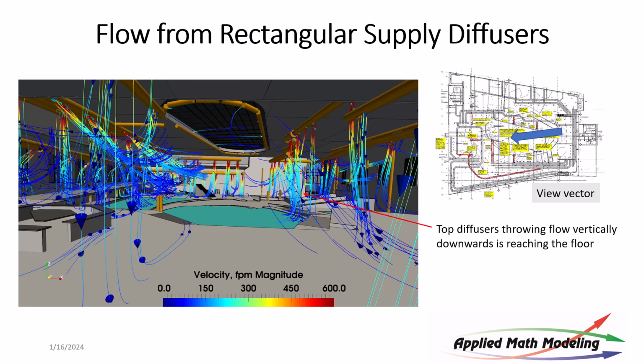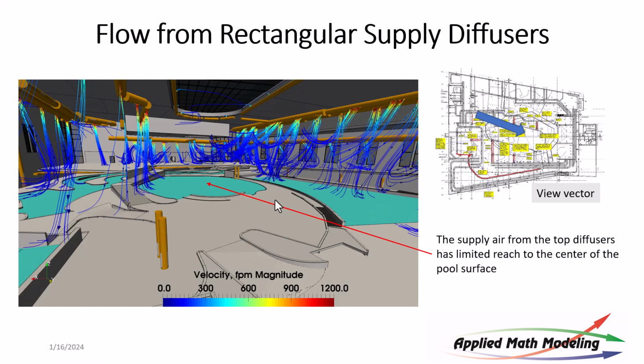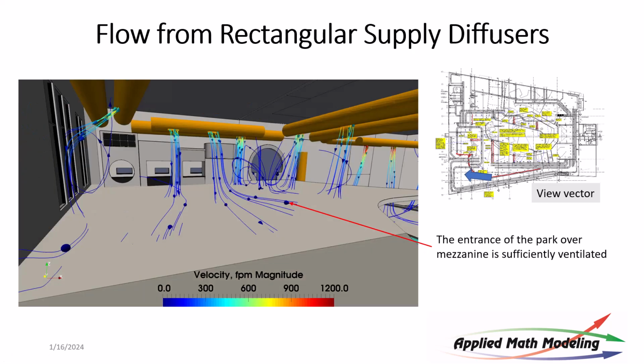As you can see in this image on the left, we're modeling air coming out of each of the diffusers in the environment. So we set the flows to be exactly what was specified in the architectural drawings and put them in the room. And then we can look at the amount of air that is passing over the walking zones. You can see a walking zone here, walking zone around here, and determine concentrations of the mixing, the chloramine gas in the air.